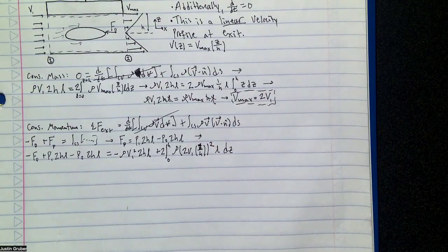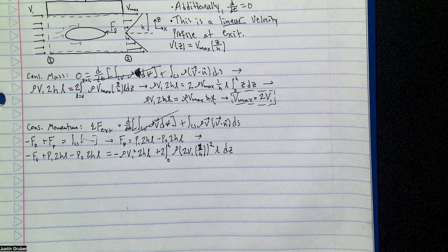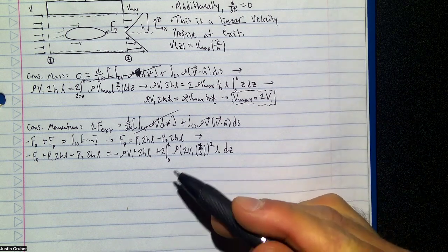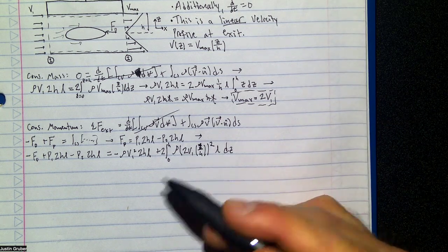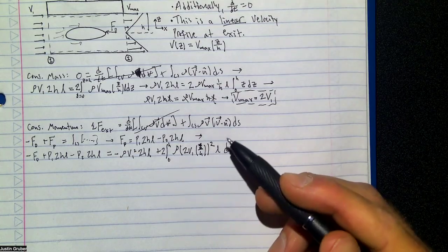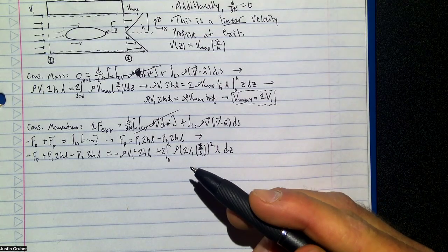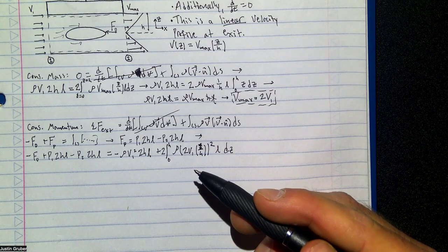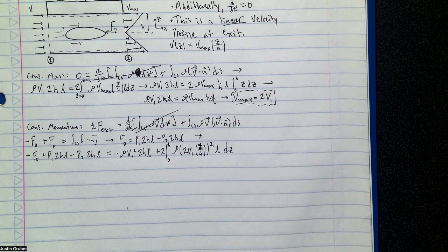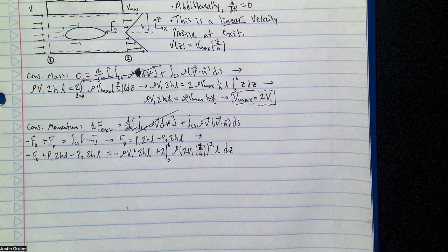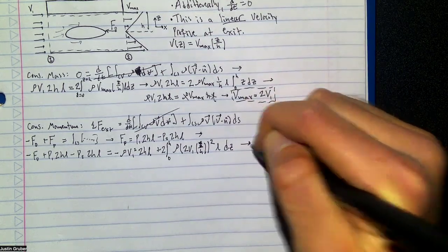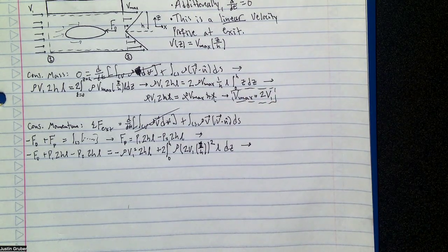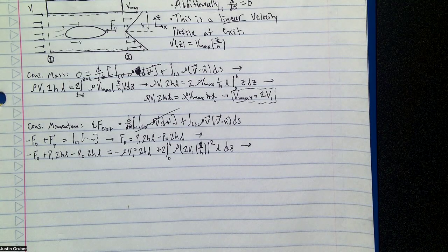Same exact thing as we just did before, except now you're squaring the whole term and integrating again. The h squared would factor out, the 4v1 squared would factor out, density factors out, L factors out. You get left with a z squared dz, which after you do the integral is h cubed over 3. Pretty basic integral. This is pretty fair game for what it'll be on an exam, I would say. It's not too bad.